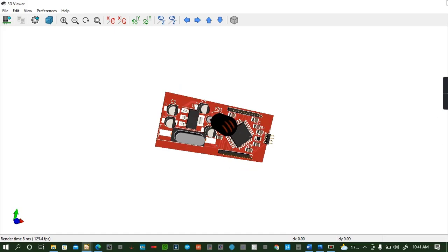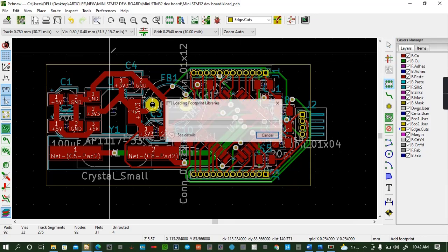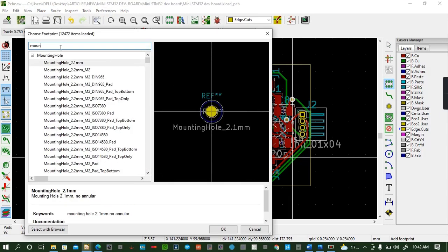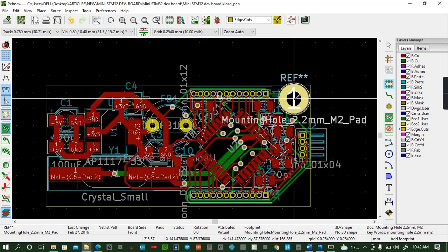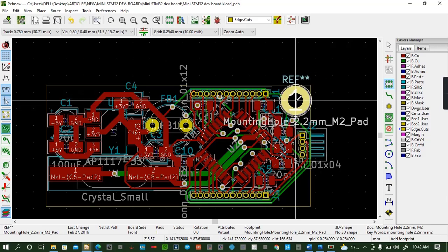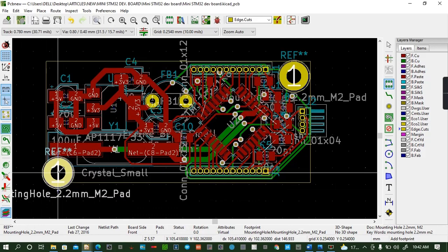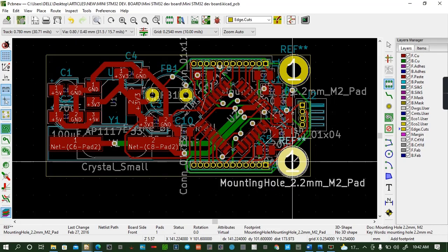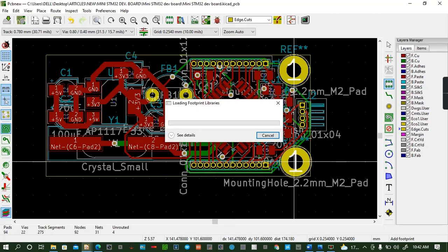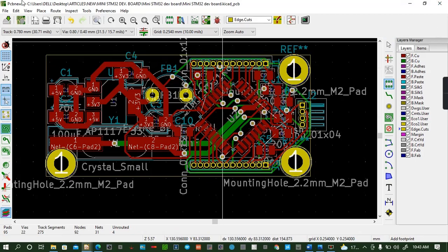The board has nice thickness, so you can finalize by adding mounting holes, so footprints. Come to here, let it load. You can add mounting holes with pad. Okay, and I can import it here. Then the other mounting hole, can import it here. Then another one, you put the final one here. You have 3 holes. Then you can click on view. You see what is happening.